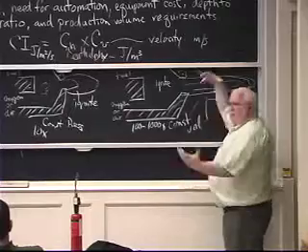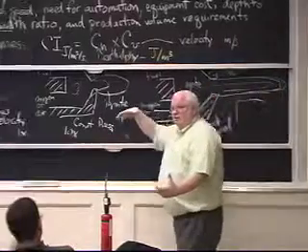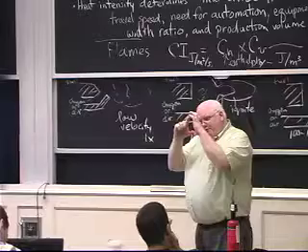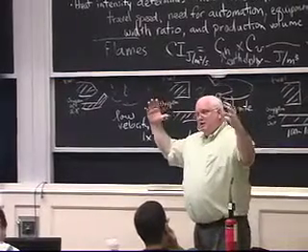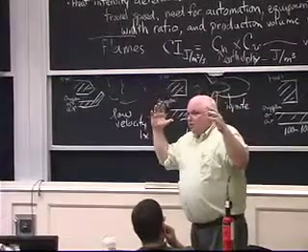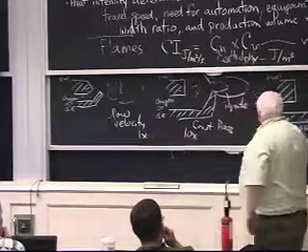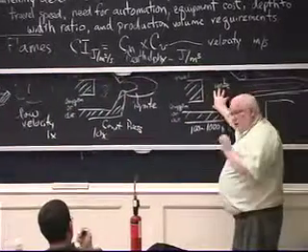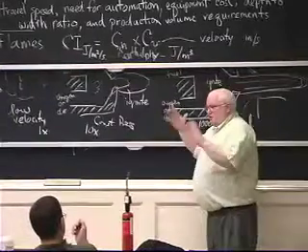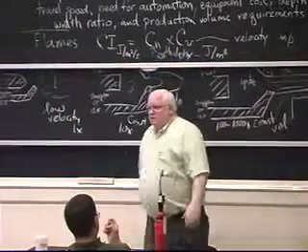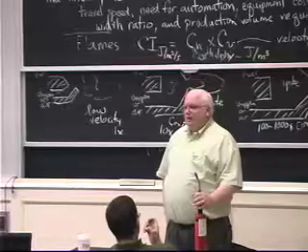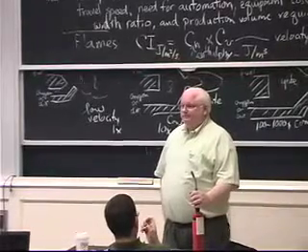An afterburner has a nozzle the diameter of the engine, and you're pumping fuel in there, not in a little combustion chamber this size, but a combustion chamber this size, which is why it burns so much fuel. And it doesn't burn it at stoichiometry either. The engine is designed to burn at something closer to stoichiometry. The afterburner is just a can, and you're doing a sort of controlled, continuous explosion.